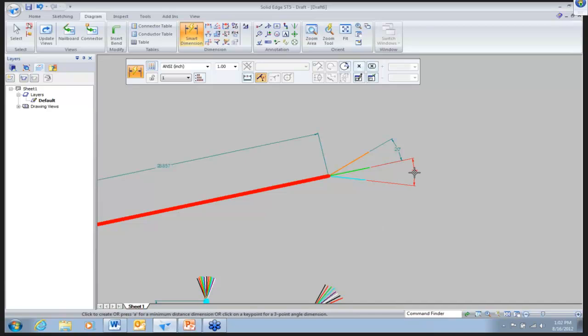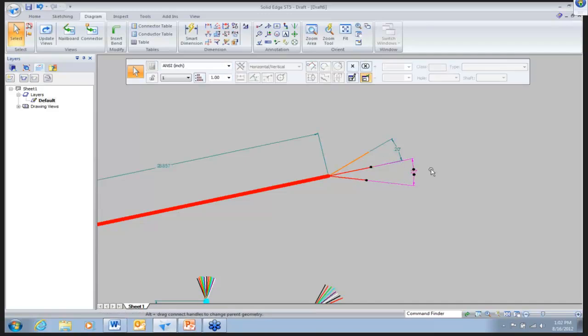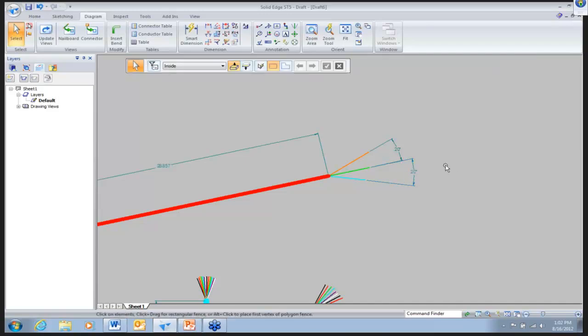And then what I said is with the new dimension thing, you can highlight over it and it'll place it in a concentric circle with it. So we can place it over here. You can see it highlights red. We click the place and now they're concentric. And if we moved one of them, it'll just move it and then they're not locked together.